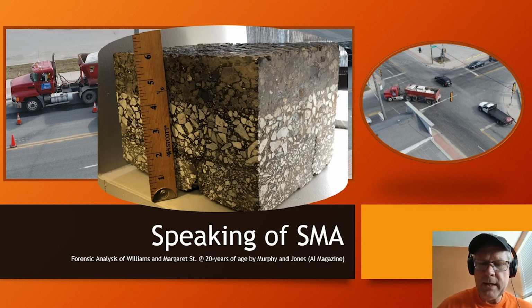You look at this and you wonder, did that crack try to come through? I'd venture to guess it did, but the stone matrix has so much effective asphalt that it's self-healing and it goes back together with passes of vehicles in the summertime. So the torture of the winter never really took its toll on this project. In this picture on the right, a drone photo, you can see there are no paving seam failures as well. It's a very good roadway. This is one of our gold standards of stone matrix asphalt performance, probably in the United States.